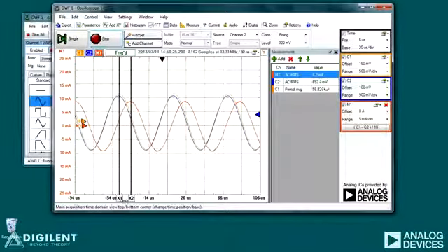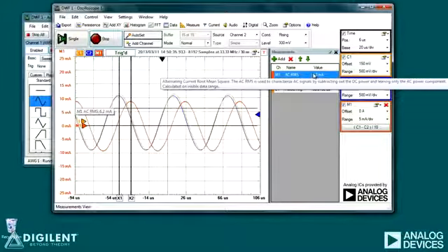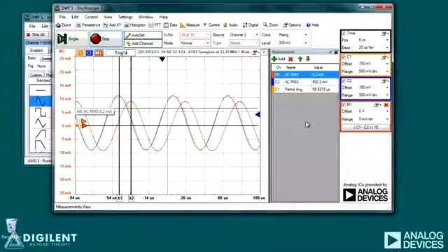The phase difference is this time delay divided by the period of the signals times 360 degrees. The average power delivered to the load is the RMS voltage times the load RMS current times the cosine of this phase difference. Since our transmission line is represented strictly as resistance, we can get the transmission line's power dissipation by squaring the RMS current and multiplying that by the transmission line resistance. Now let's take a look at the result of all this number crunching.